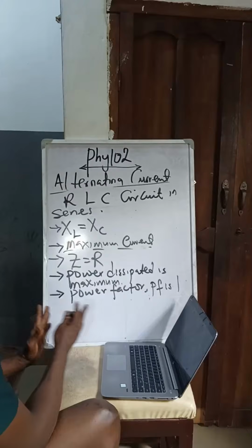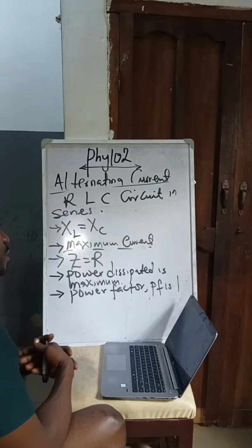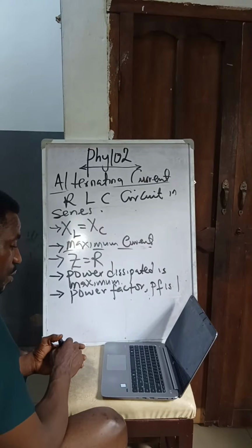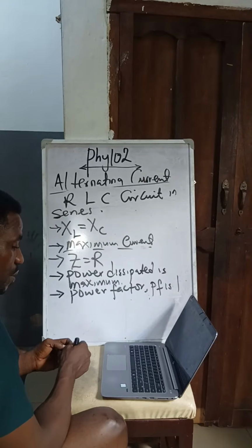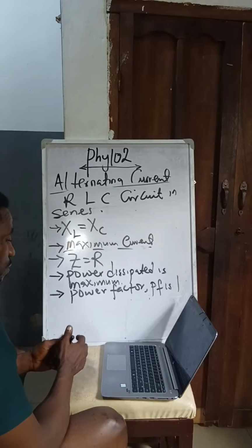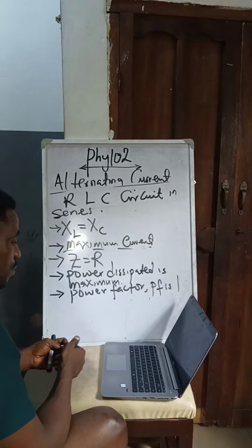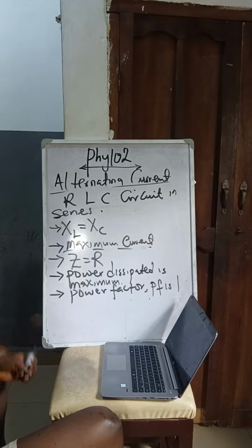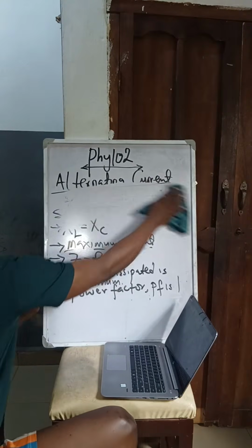So this is the condition for resonance in an RLC circuit. Igwe Nancy, you're correct. That theta is the phase angle difference. To find it in an RLC circuit, we use tan inverse of (XL minus XC) all over R. So these are the conditions for resonance in RLC series circuits.